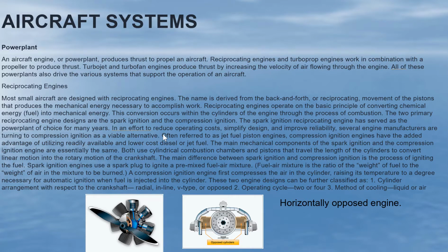In an effort to reduce operating costs, simplify design, and improve reliability, several engine manufacturers are turning to compression ignition as a viable alternative. Often referred to as jet fuel piston engines, compression ignition engines have the added advantage of utilizing readily available and lower cost diesel or jet fuel.